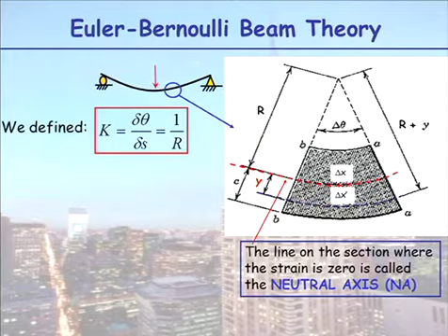Okay, I have a beam in here. We have the depth of the beam here. This red line represents the neutral axis. The neutral axis of a section is where there is no stress occurring at all in the beam, and generally that coincides with the centroid of the section when you just have bending. I fit my radius r to my circle.